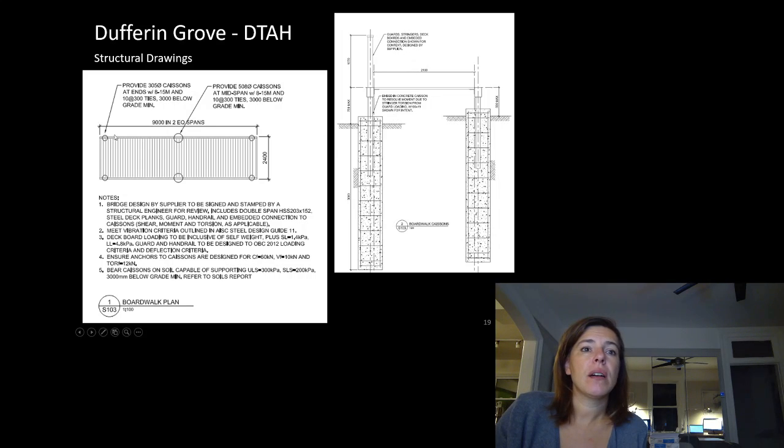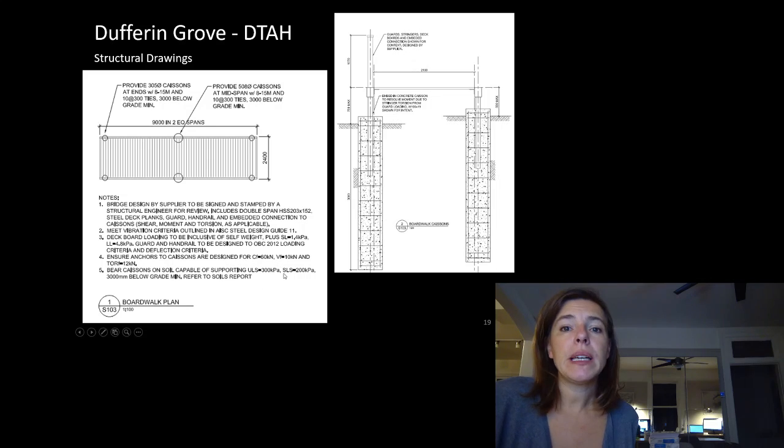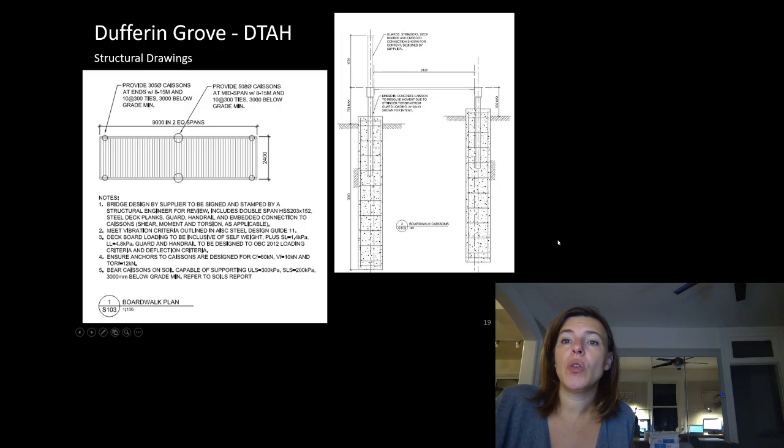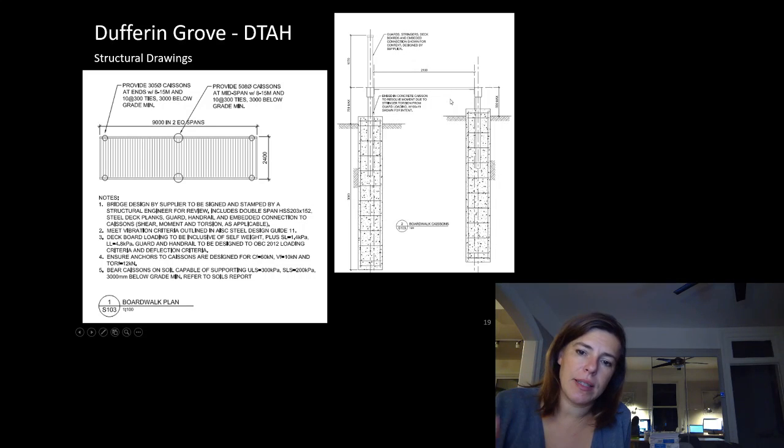And so in the end, here are the drawings. You can see that we had, can you see it? Yeah, so there was soil criteria. The soil was really crappy in the upper reaches of this project, and it was really good down low. Luckily, the common type of foundation for small elements like this is caissons or sonotubes with reinforcing. So that worked out really handy because that was the exact appropriate solution to solve our soil problem, and it's the typical kind of precedent for designing these foundations.